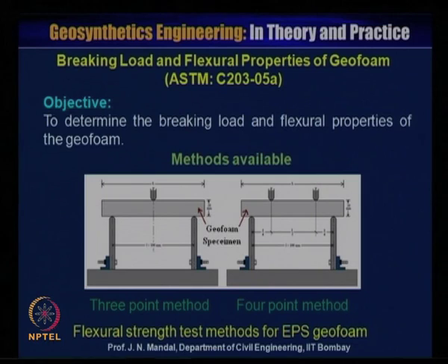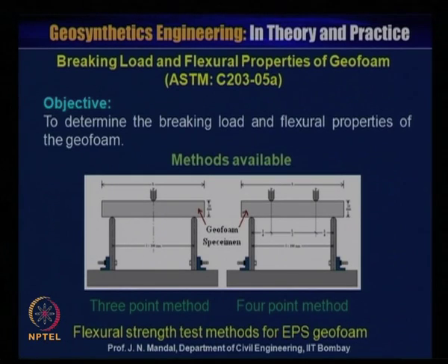Now, breaking load and flexural properties of the geofoam as per ASTM C203. The objective of this test is to determine the breaking load and the flexural properties of the geofoam. This is also a very important parameter. The methods available are the 3-point method and the 4-point method.